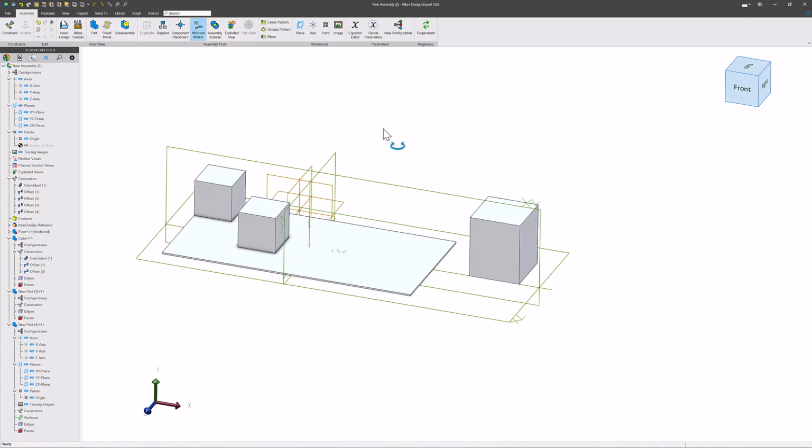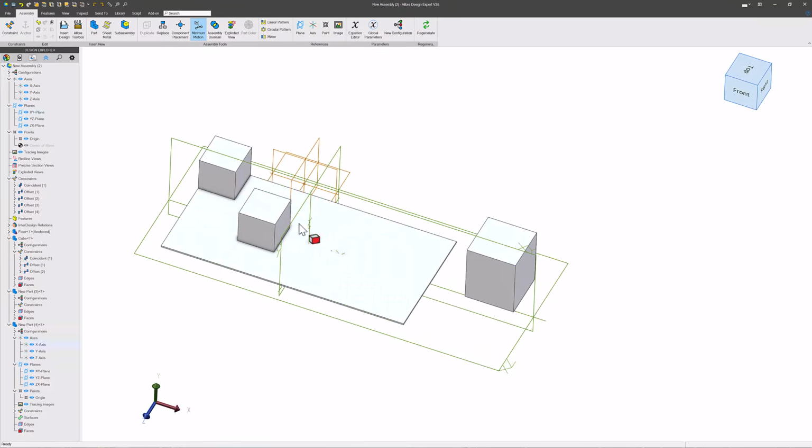So the rule for me is you can avoid all of this trickiness by inserting a part and then, whenever possible, using the regular assembly constraints and not edit in context features. So just kind of like when you're making a sketch and the fewer dimensions you use, the better. So it is with this. Editing in context has some amazing results, and those results are best realized when we use them as little as possible because the standard constraints are more reliable, more predictable, and then we build a better foundation using constraints to highlight the benefits of what those edit in context features are.